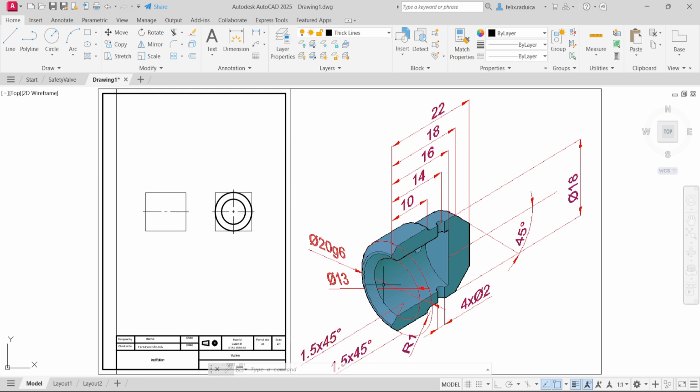Additionally, we have against the diameter of 13 a chamfered edge of 1.5. So it gives us an extra circle with a diameter of 16, but since we are at a 2:1 scale, we'll draw with a diameter of 32.